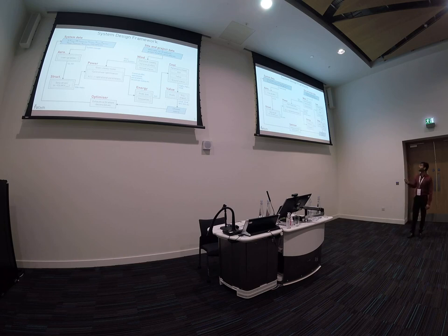Then the other type of inputs is the site and project data. The two key inputs within that are the wind resource and the energy price mechanism. The wind resource input to the power computation model leads to the energy profile of the particular system that we defined here. The wind resource characterization also includes the vertical wind shear profile. We are also developing a parametric cost model, which models the key scaling functions of the main factors of the kite, tether, and the ground station. I will tell a bit about this also at the end.